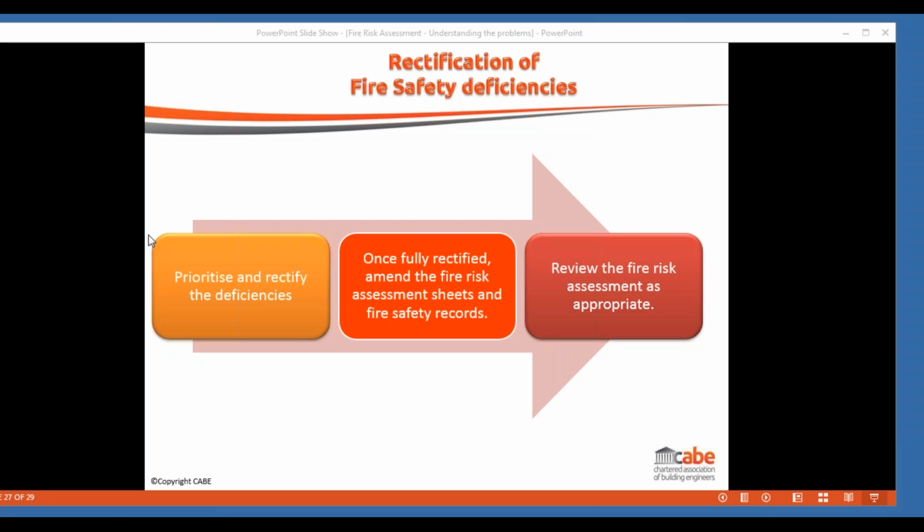Okay, would a management flat over a pub need to be covered by a fire risk assessment? Does the RRO apply to this? In essence, the actual living accommodation, because nobody's employed whilst they're in it, or although it may be an employee that's occupying it, in practice the flat isn't covered. But because it's all within one building, and particularly within something like a management flat in a pub, the flat probably hasn't got the same level of separation between the living accommodation and the commercial use that you would find in a block of flats where each flat is its own compartment in effect.